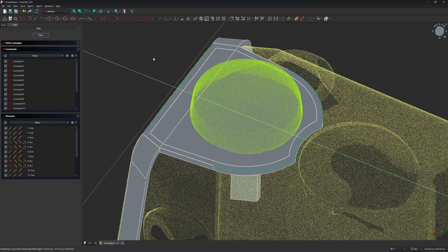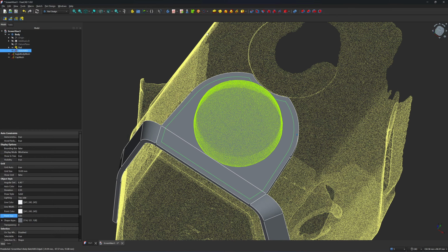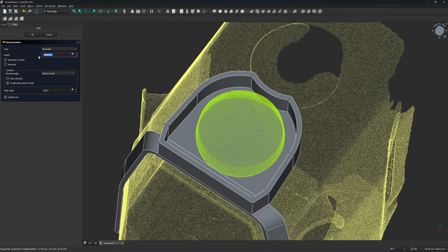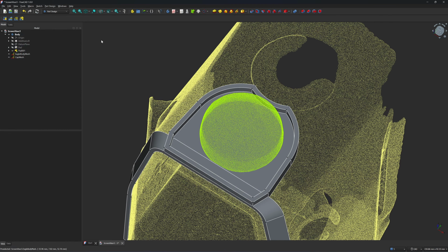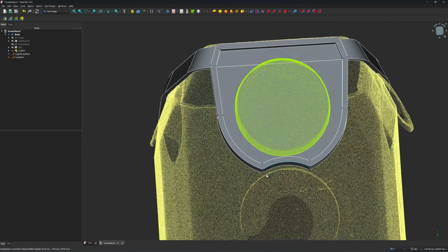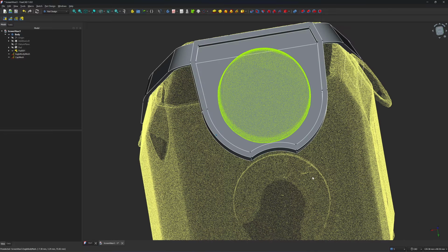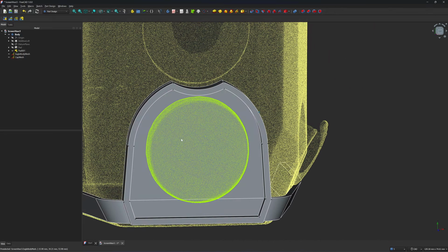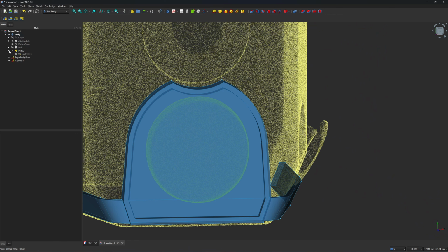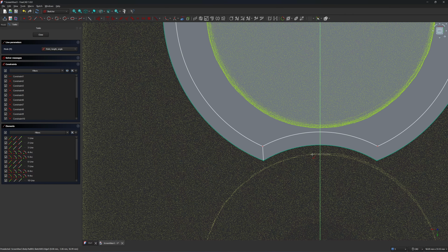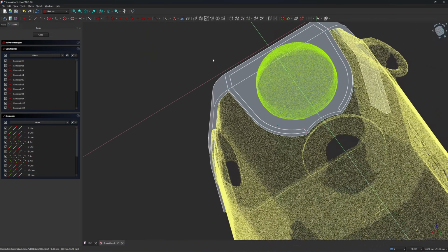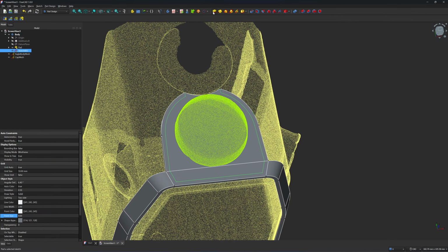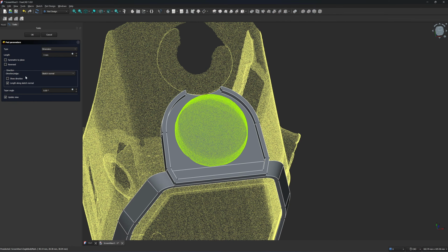Next I'm going to close it. And then I'm going to extrude it for 3 millimeter. Click on OK. But I don't want this part to be extruded because I want to print it in this direction and I don't want to have a support. So I will go back to the sketch from this point to this point, from this point to this point. Okay, then I will close the sketch. Pad 3 millimeter. Save it.